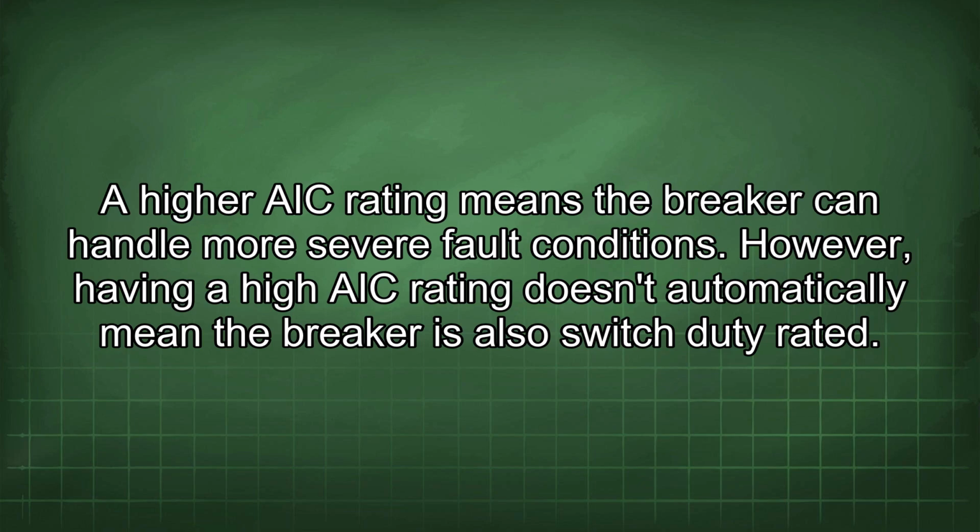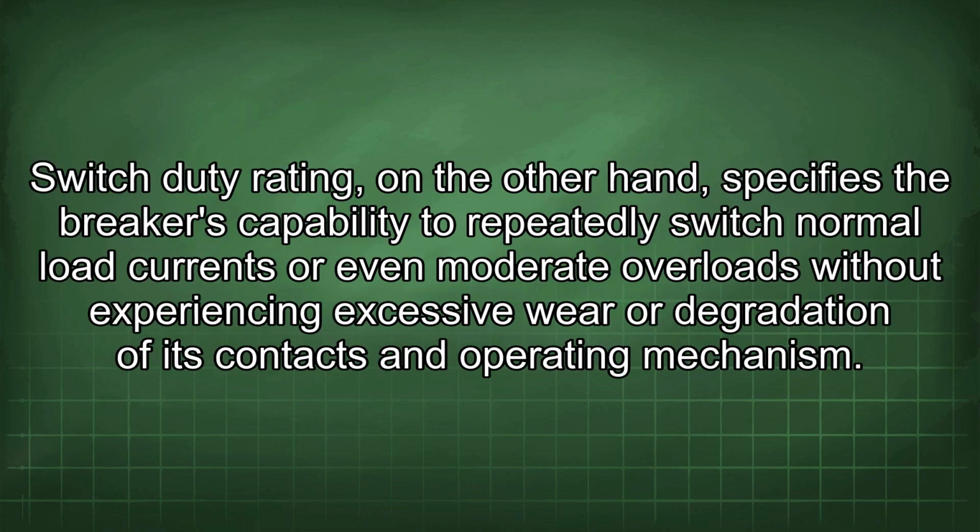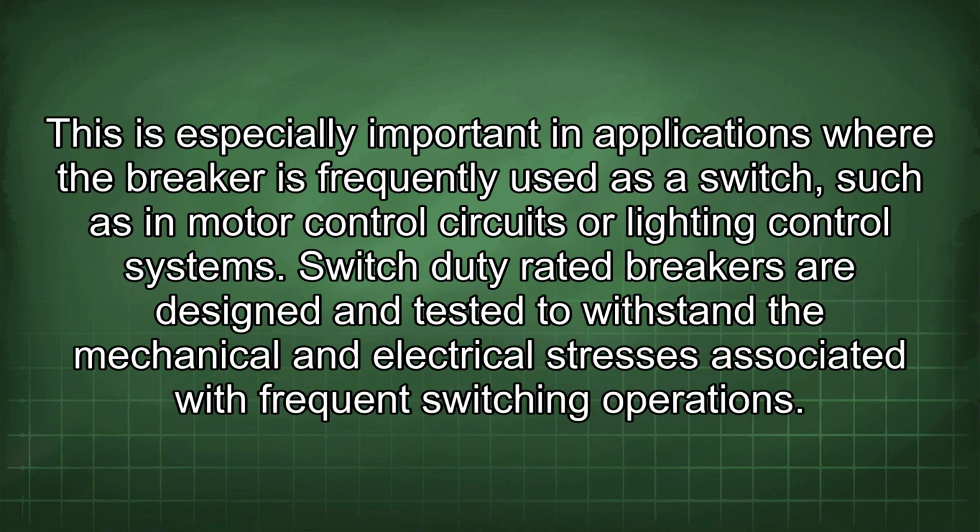However, having a high AIC rating doesn't automatically mean the breaker is also switch duty rated. Switch duty rating, on the other hand, specifies the breaker's capability to repeatedly switch normal load currents or even moderate overloads without experiencing excessive wear or degradation of its contacts and operating mechanism. This is especially important in applications where the breaker is frequently used as a switch, such as in motor control circuits or lighting control systems. Switch duty rated breakers are designed and tested to withstand the mechanical and electrical stresses associated with frequent switching operations.